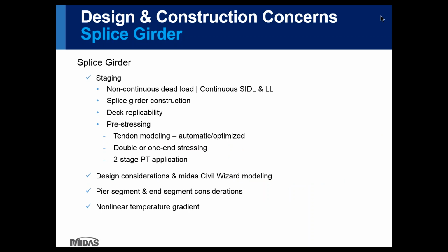So some of the design and construction concerns regarding the splice girder application, in terms of staging: running the dead load non-continuous and superimposed dead load and live load continuous, spliced girder construction, and deck replaceability, pre-stressing for tendon modeling. As mentioned before, you can do it automatically or you can optimize it.